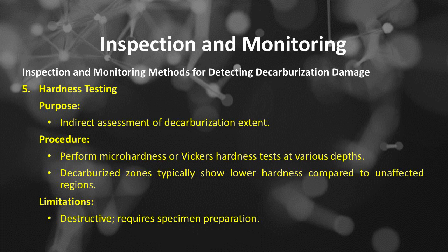The purpose of hardness testing is indirect assessment of decarburization extent. The procedure is to perform microhardness or Vickers hardness tests at various depths. Decarburized zones typically show lower hardness compared to unaffected regions. Limitations of hardness testing: it is destructive and requires specimen preparation.